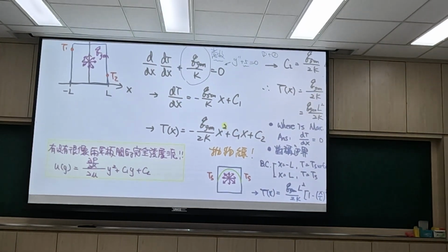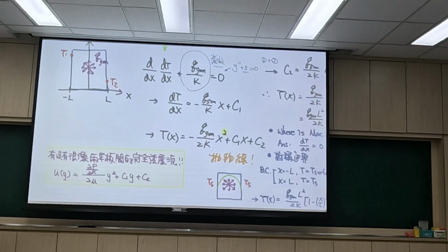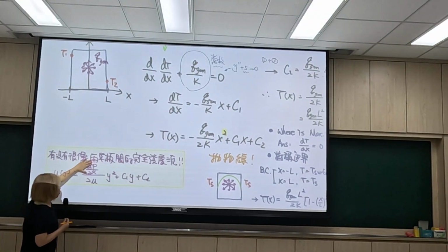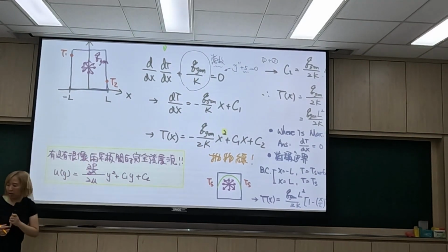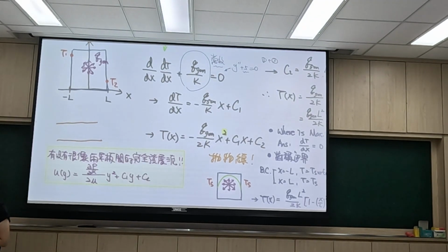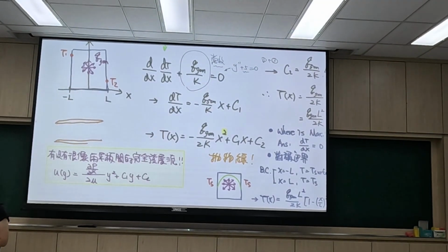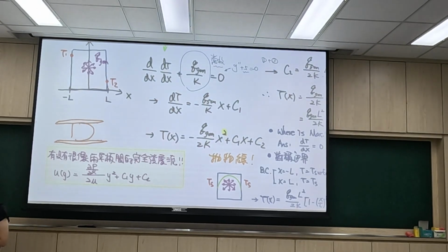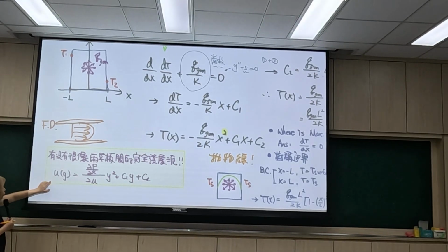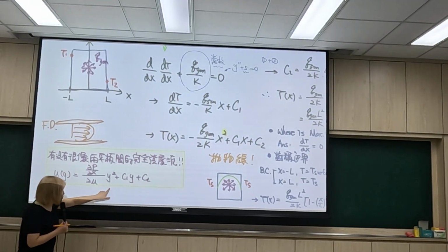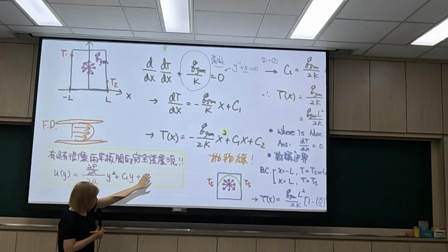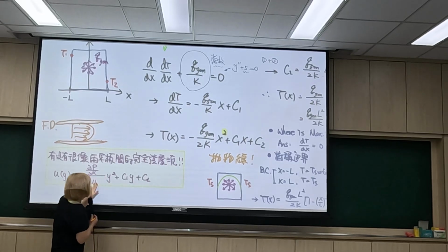And remind you, in fluid dynamics, this is quite similar to developed flow between two plates. That's two plates, then you have a flow with a parabolic profile. In fluid dynamics you write down your velocity profile in this form, which is also a parabolic profile, with C1, Y, C2. So it's really, really similar to each other.